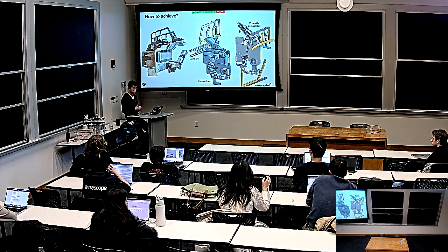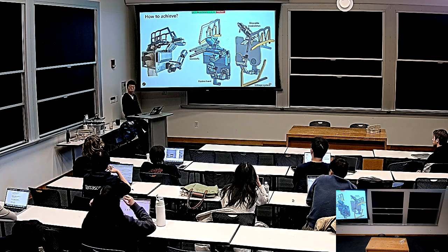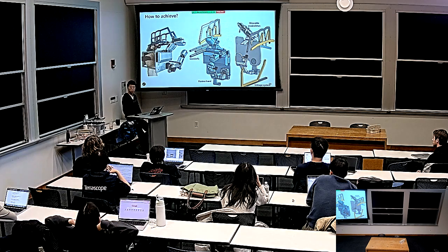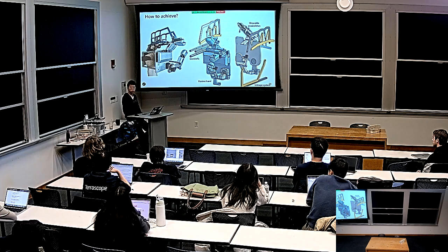Another thing is, when we are collecting data, the visual observation still has some mismatch issue with the real robot. Although it could be solved by, for example, the pre-train and fine-tune paradigm, it still requires you to collect a data set, for example, with a limited amount of teleoperated data. Yeah, so those are the 2 main issues that I could see.